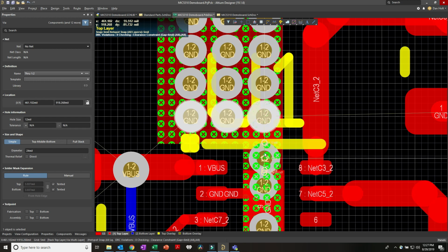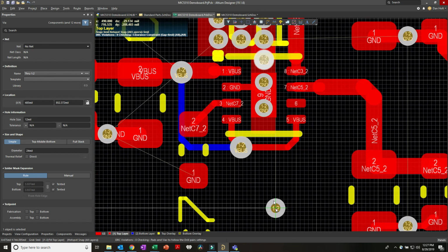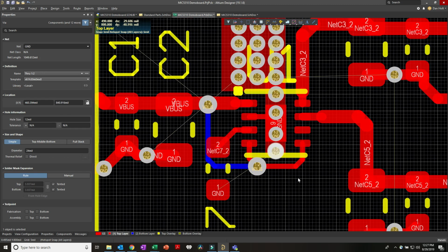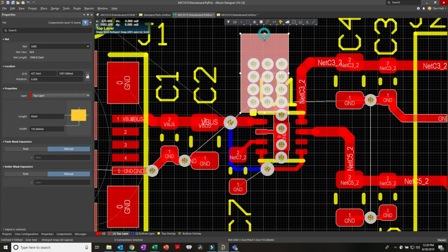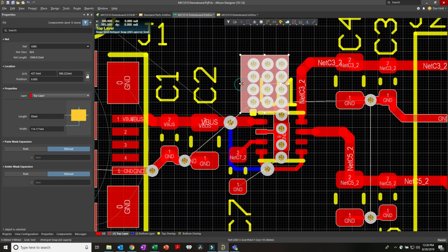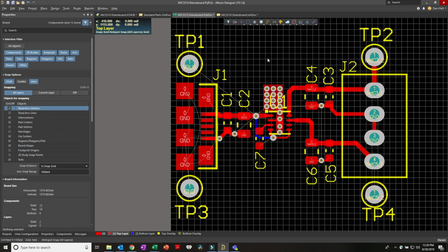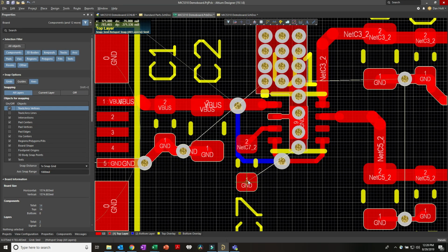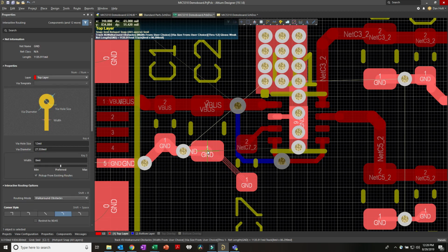So if I do the same thing here, well, let me just copy these three, Control C, and I'll just leave the reference point out here. There's nothing to get in the way for it to jump to. And now I can just come up nice and clean, copy to there. But if I want to duplicate that spacing, again I can press Control C and copy the spacing. And if I do a Control V, you can see now I'm doing that. But these are all symmetrical, so spacebar, or I could just say mirror on the y-axis. Let's see, I'm pressing Y, does that, and I can highlight that guy.